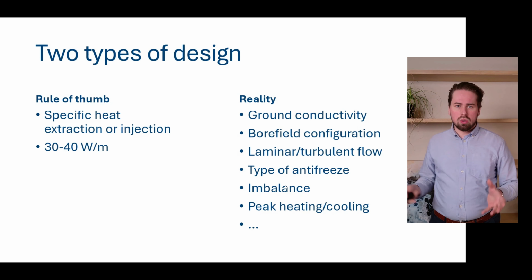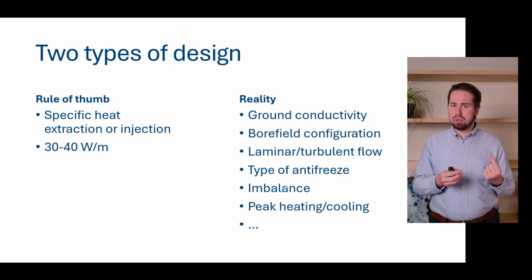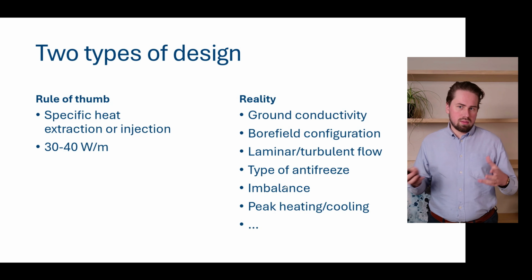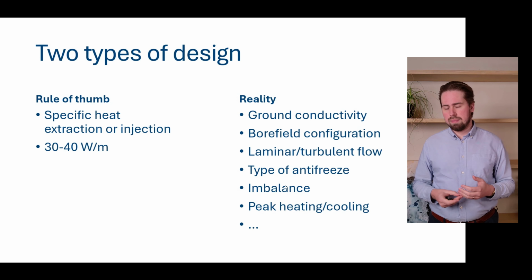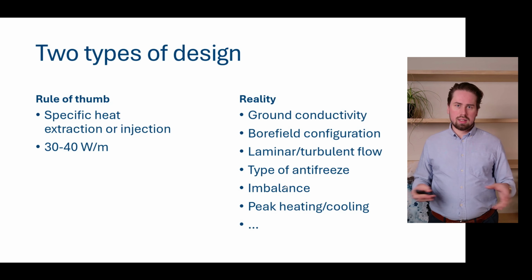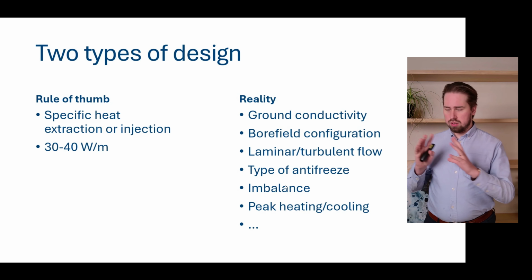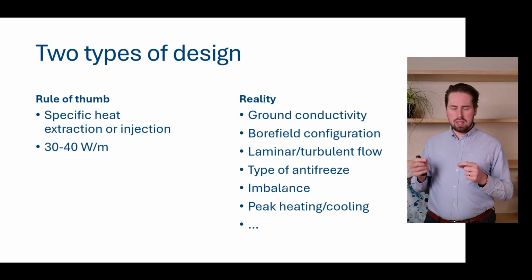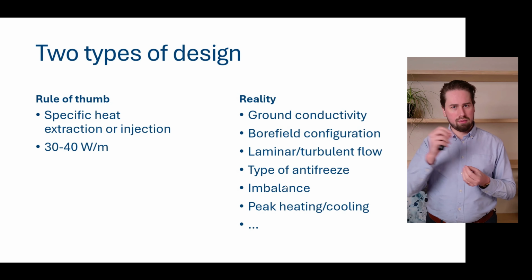And this whole reality you're dealing with when you're a borefield designer is not captured in this simple one number that determines your total borefield size. And even when this is clear, rules of thumb are still used quite a lot in industry. Which is why we decided to do some research about it, and we simulated 3 real-life buildings, an auditorium, an office building, and a residential building, in a dynamic simulation software to get a really precise hourly profile out of it. So we know the heating and cooling demand of these buildings at every hour.